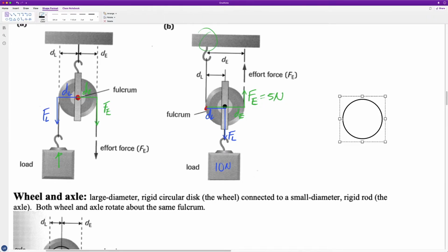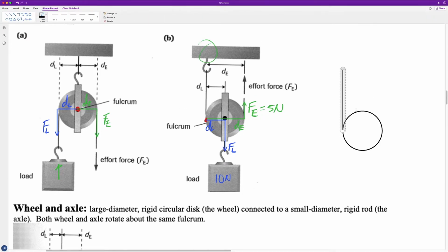All right, so let's say this is our pulley. So that's the string on the left, and here's the string on the right. So let's say we want this thing to move up by the equivalent of this distance here. So we want to move it up by the length of this disc. Well, in order to do that, we have to shorten both sides by this amount. So on the left string, we have to remove this amount of string, and on the right hand side, we have to remove the exact same amount.